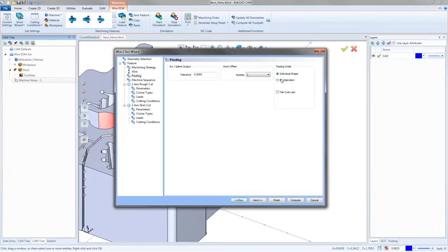You can do individual shape, which means if I'm cutting 10 shapes, it's going to cut 1 at a time. Not only is it going to cut 1 at a time, it's going to do it in the order that I set it up to cut in. So it's going to rough, then skim 1, and then move and do a rough and a skim on another. You could also say go by operation. So by operation is going to go in and rough everything out and then come back and do a skim pass on everything. So that would be how you break it apart based on, you want to get rid of all the rough material and just let the machine finish the part. The by operation is going to work well for that. So I'm going to leave it on individual shape and then go next.